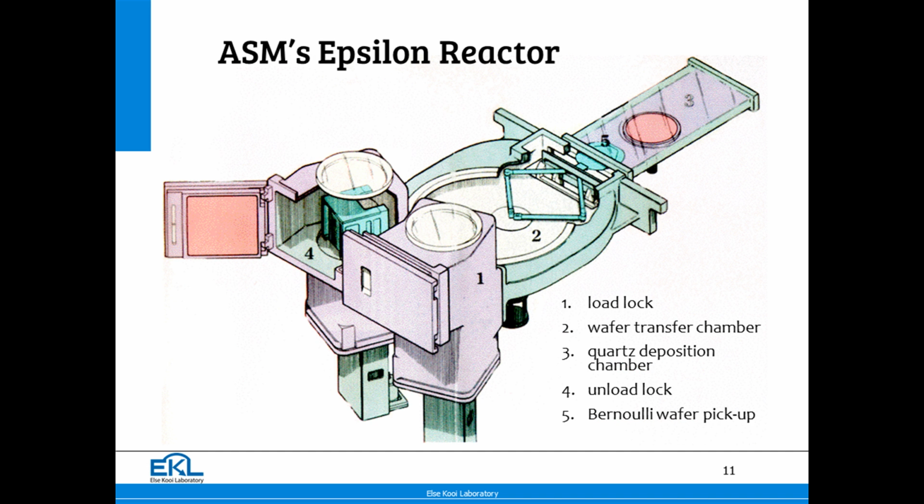And then the last one, quite a deviation from what we had before. You still recognize the horizontal reactor. This is the reactor part. I did not draw it, it's heated by infrared tungsten lamps that are not on the drawing. Single wafer, quite a deviation from what we had, because till that time we had batch reactors. Rotating susceptor, a single wafer, so extremely good uniformity.